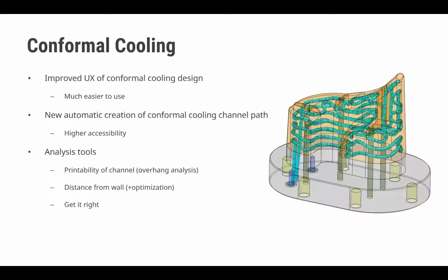So this conformal cooling is something that was brought out in version 14, but has been vastly improved in version 15 with improved user experience, making it much easier to design and develop your cooling channels as such. Much more automation with regards to how these cooling channels are being developed. It's much easier to define the area which you want to cool, with advanced analysis tools as well for